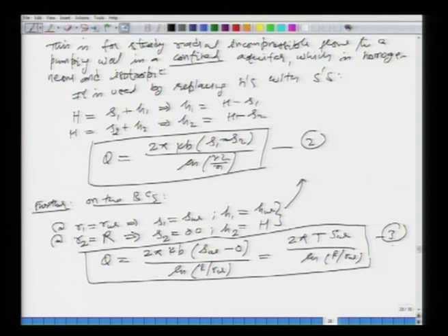See, the advantage of this equation 3 which we have just derived is what? Is we can find out the aquifer property T. This Q is actually we would know, because we are pumping certain amount of water. So, we know the rate of pumping at the pumping well, right. So, if we want to find out the aquifer properties, right, so then you can get T from this equation. How? Well, all you need to do is you just need to observe the value of drawdown at the well, all right, and you already know the radius at the well, and you also need to know the radius of influence. So, knowing all these things, you can find out the transmissibility of the confined aquifer. Okay.